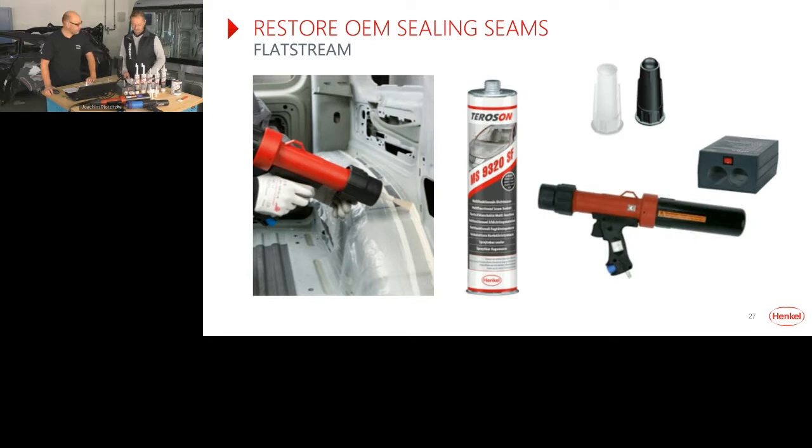Especially for this, we need a high pressure as mentioned. And once again, I grab this tool, I like it. This tool has a pressure ratio from 1 to 3. That means 1 bar pressure inside the inlet gives you 3 bar working pressure.